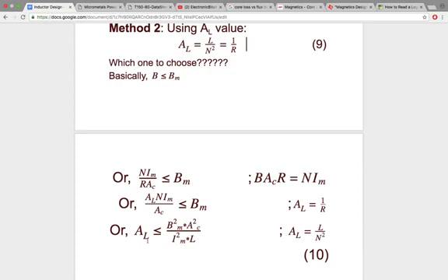But if this is greater than the required permeance, your reluctance is low, lower than the reluctance required. As a result, for the Im current flow, the B in the circuit will exceed Bm, and the inductor may go into the saturation region.